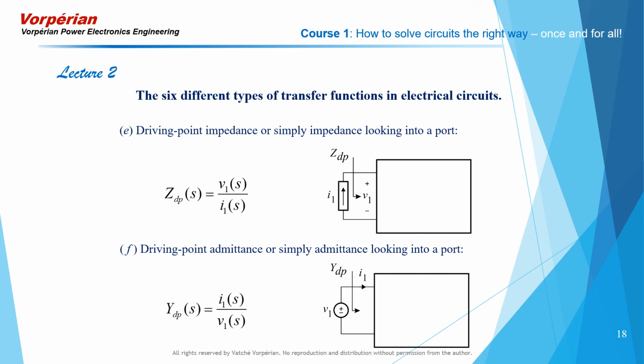Its reciprocal, the driving point input admittance, is determined by applying a voltage source at some port and studying the current going into that port in response to that voltage V. That ratio is known as the input admittance. So if we are going to think about the input admittance as a transfer function, we have to say that its excitation is a voltage source.